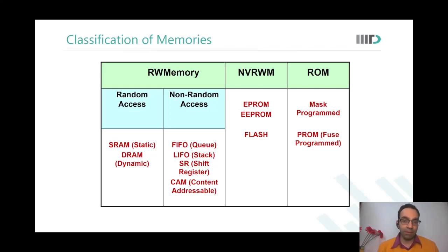Similarly, because we are in the memory design course, let us say there is some location inside the memory that is failing. I can add some additional redundant memory in the overall chip and say that if this failing location is addressed, then instead of reaching out to that failing location, go to this replacement location. This again is programmed by using PROMs. Okay, sir, thank you. Anything else?